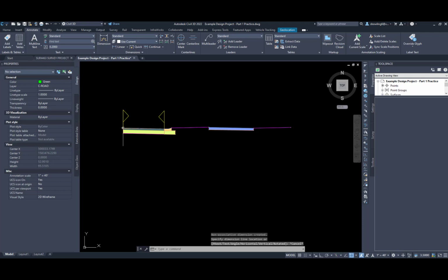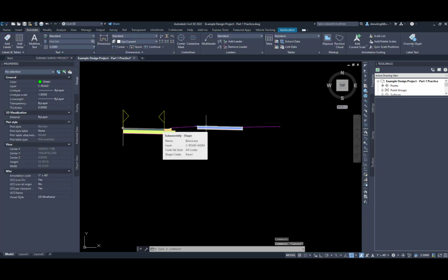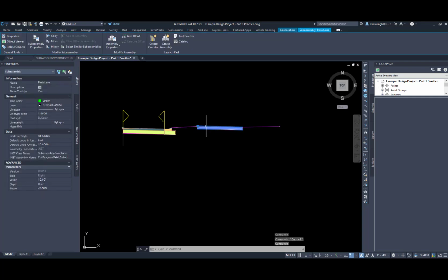Okay. The next one is the 7-foot grass strip. So I'm going to click on it, come over here in its parameters, and where it says 7 feet in the width, I'm going to change that to 6. The reason it's 6% is to make sure that it drains properly and it's not squishy when you walk across it. I've seen people do it at 1%, but I know Osceola County's code is 6. And I've also seen people approve it with 1, but let's go on.